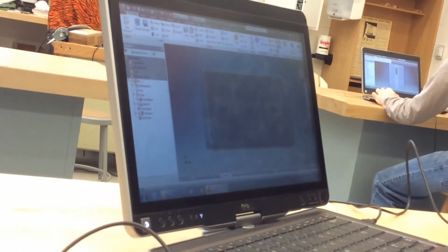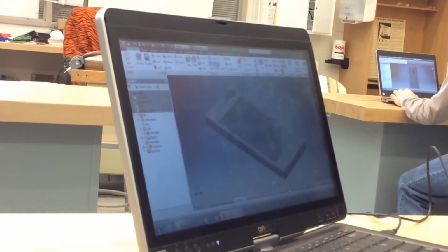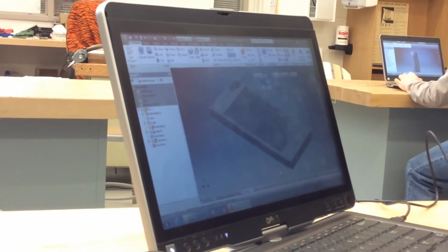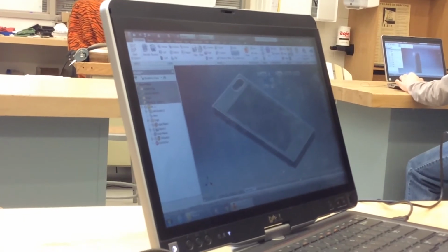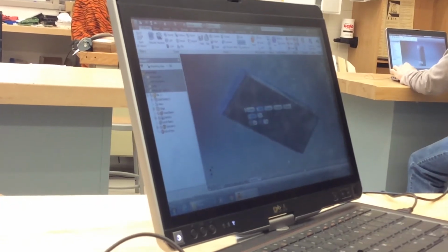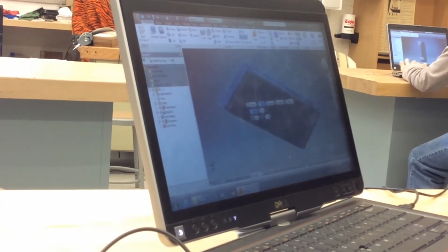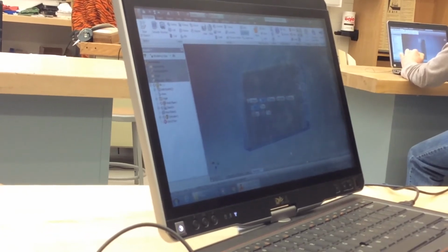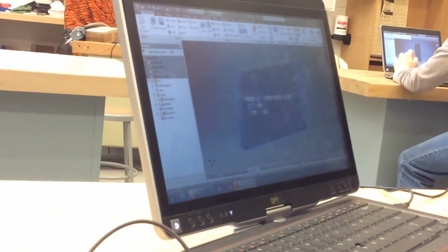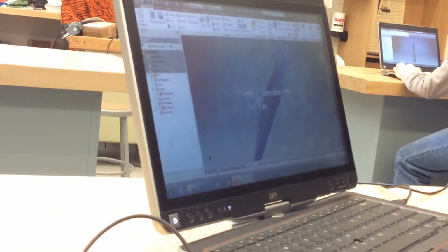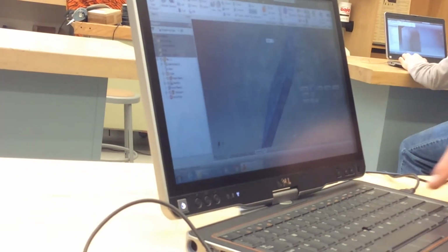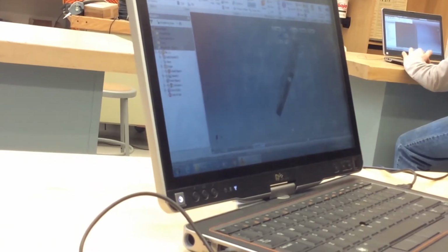And I want to make all of this bigger. So I'm going to go over here, direct, alright, size, faces, offset. 1, 2, 3, 4, 5, 6. That one selected. Now I select the 6 sides. I'm going to start pulling this off. And I want this to be 0.050, or 50 thousandths. And it gets bigger, 50 thousandths in all directions.